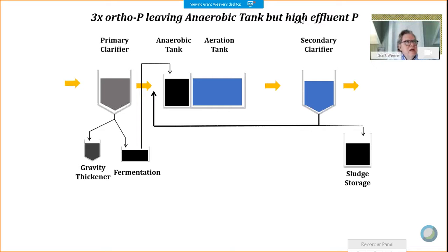It's a tool that I've used many times, particularly in plants not designed for phosphorus removal. We start creating dead zones on purpose, okay? Obviously, those dead zones need to be periodically resuspended. If they're allowed to be dead zones for too long, you're going to lose mixed liquor there. Your mixed liquor concentration will drop, to the detriment of the overall plant performance. And the solids will sit there so long that they start to decay and release phosphorus in a non-beneficial way.